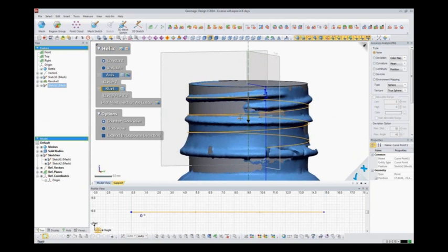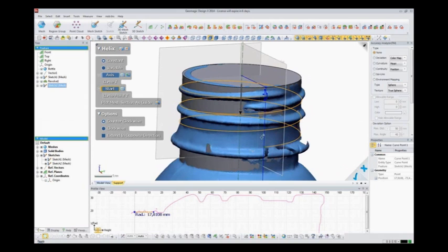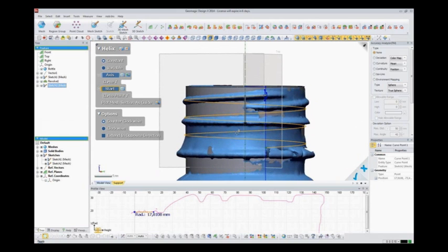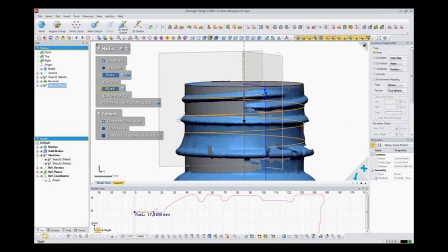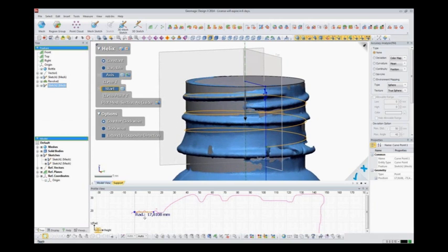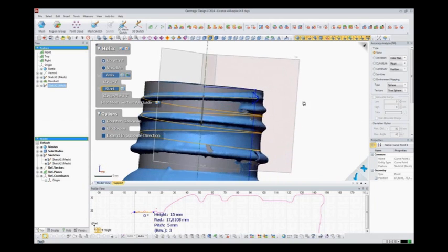And then we can draw the helix profile, the sketch profile on here, and we can see every point should match one of the ribs here. So that's 360 degrees should be on the next rib here. So we could say we have our radius here, and we have our height, and we have our pitch and number of revolutions, clockwise and counterclockwise in this case.